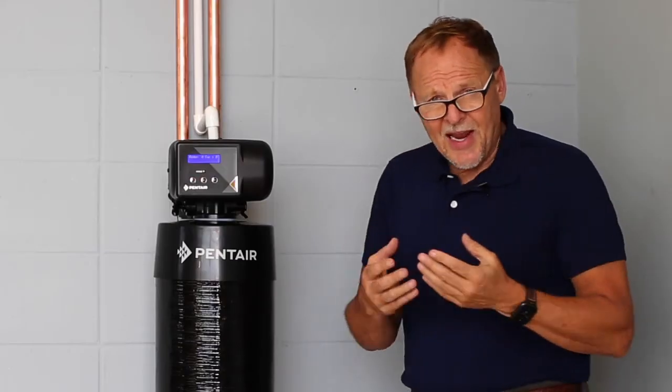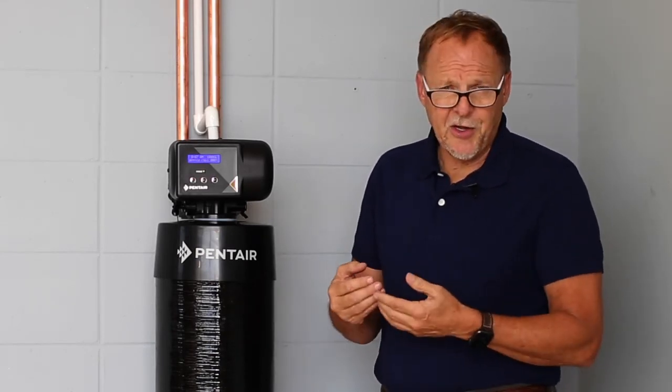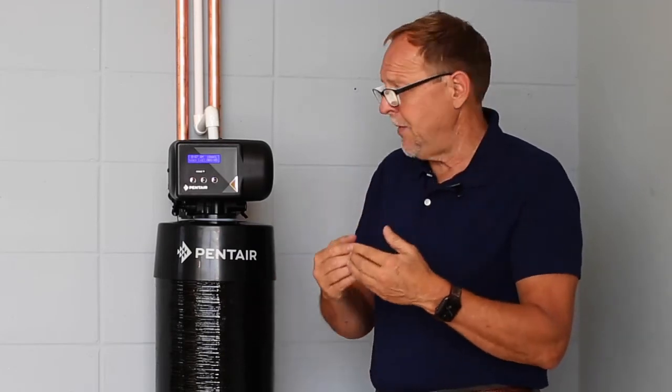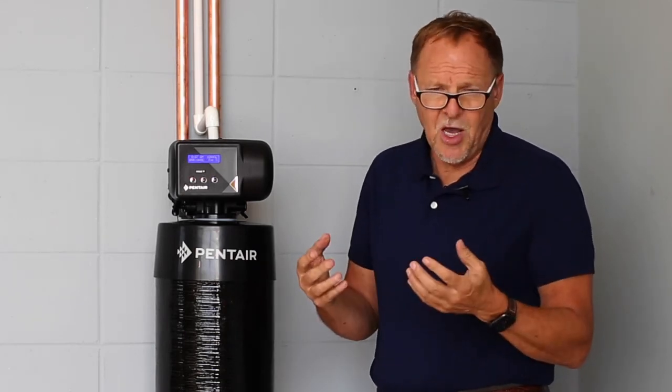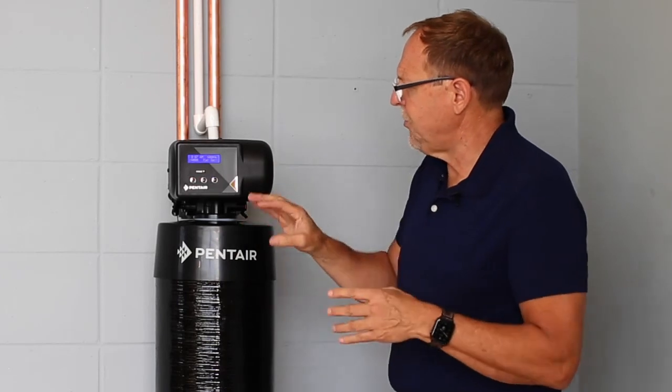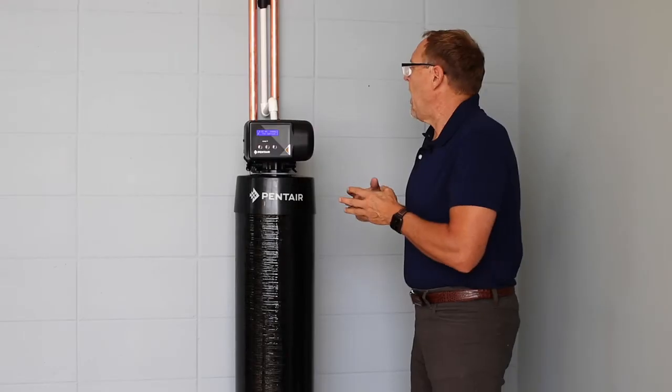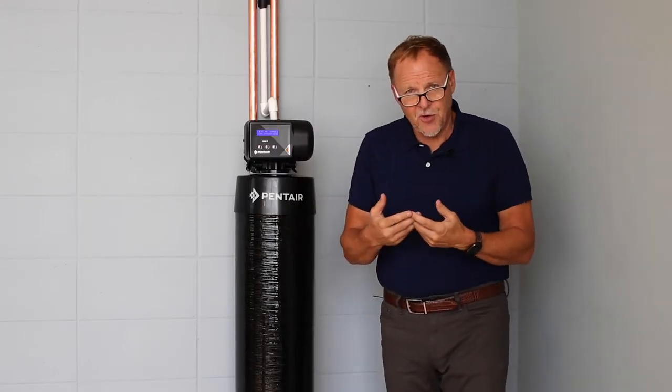And after that, the next thing I have to do is just explain the expectations to the customer. Remember, if it's a carbon filter, the mineral will have to be rebed, but it's going to be several years from now. So that's the only maintenance they're going to do in a few years, is actually have a serviceman come out and rebed the filter. If it's a neutralizer filter, they may have to actually add mineral to it every year, depending on the level in that tank. But these are things that the serviceman will do once he's on the job. So carbon filters, neutralizer filters, same programming, very simple. Just make sure you also explain the expectations to the homeowners.